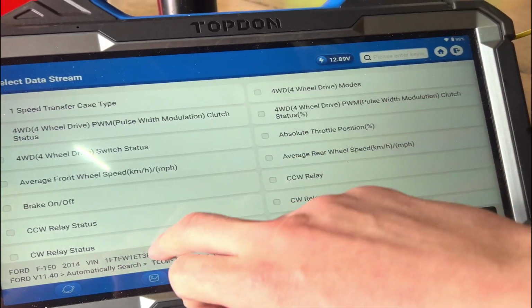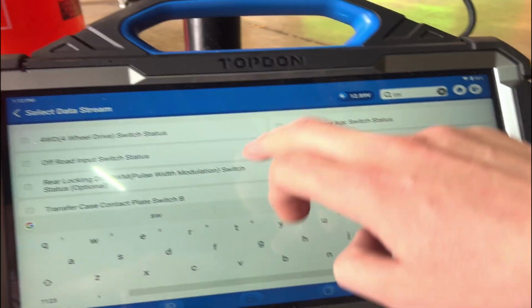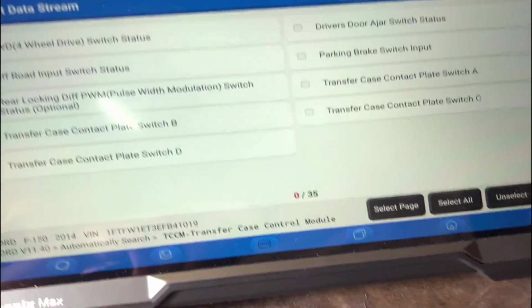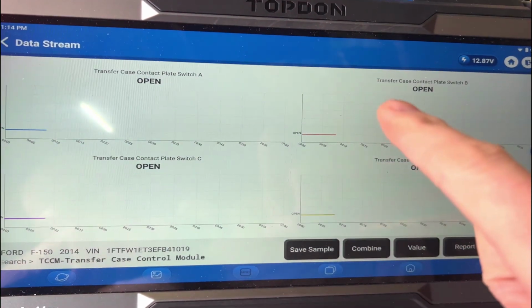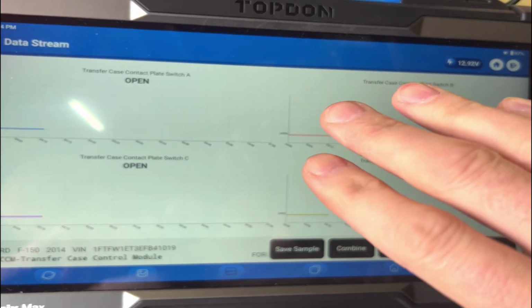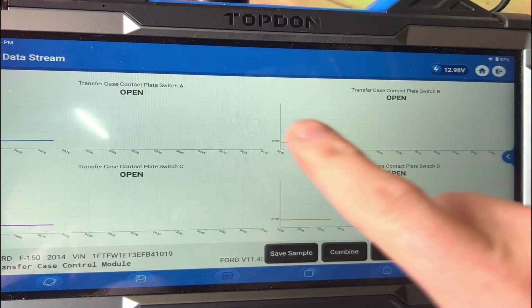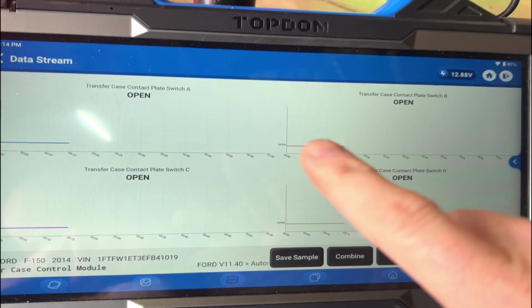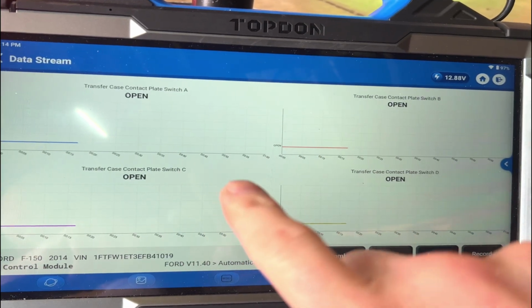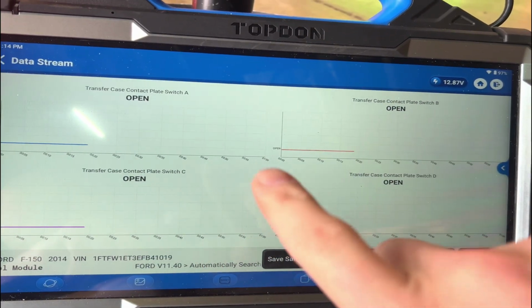And then I think it was our switch. Let me pull this up. Okay, we have our 4 switches graphed, which is interesting that they are all open. Let me show you why, and that we're not getting codes for this before we actually try to actuate the motor. All 4 positions open. We've got our lead in there. Test light still connected to ground.